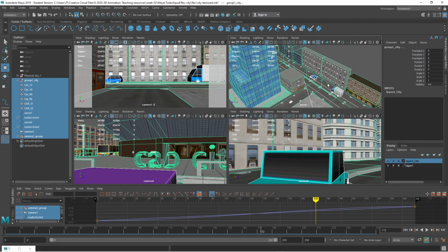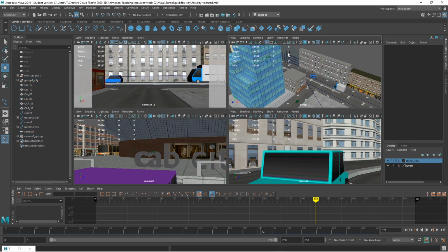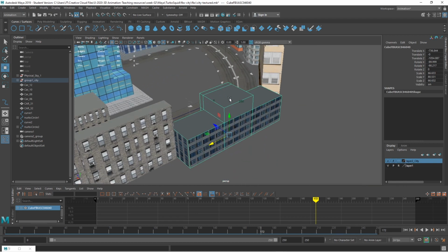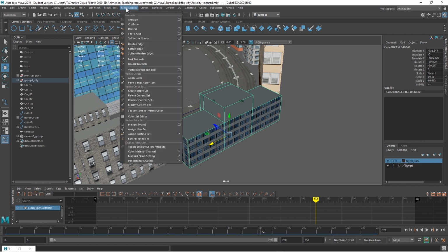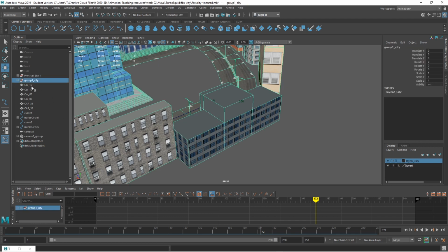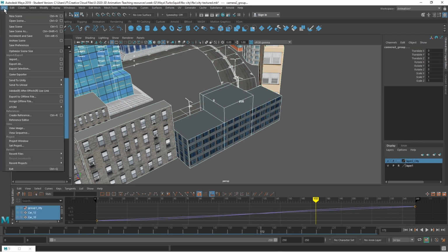So if I find the building that it's doing it with, I need to get the layer selected, so I can press F on that now. And what I need to do is, if I go back to modeling, I should be able to reverse normals on that. So normals, reverse. So I click on that. Nothing actually looks like it happens here, but when I re-export that, just enter Unity selection.